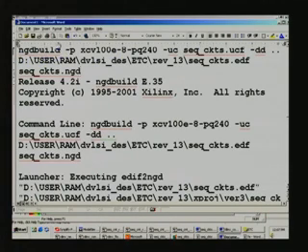Let us not go into the details of this. It has taken XCV 100 as the device that we had already mapped in the synthesis, and we also gave the user constraint file. This is the option here for that, and we really do not have to worry about all these commands unless you give it from DOS. So, here what is essential is what they mean.